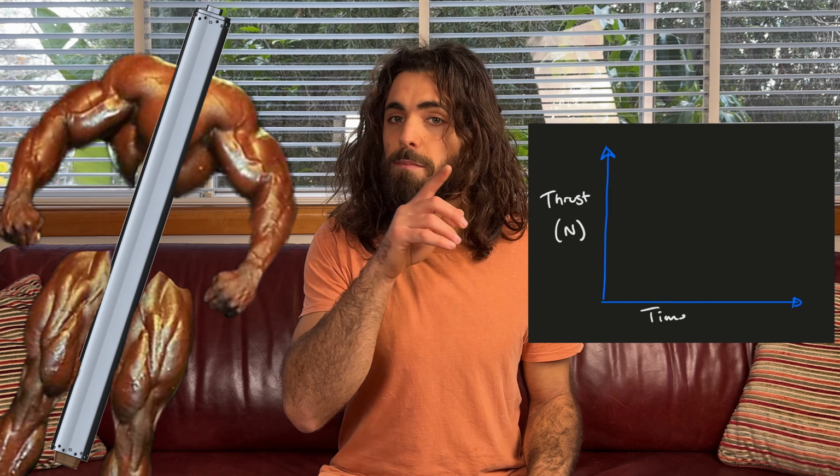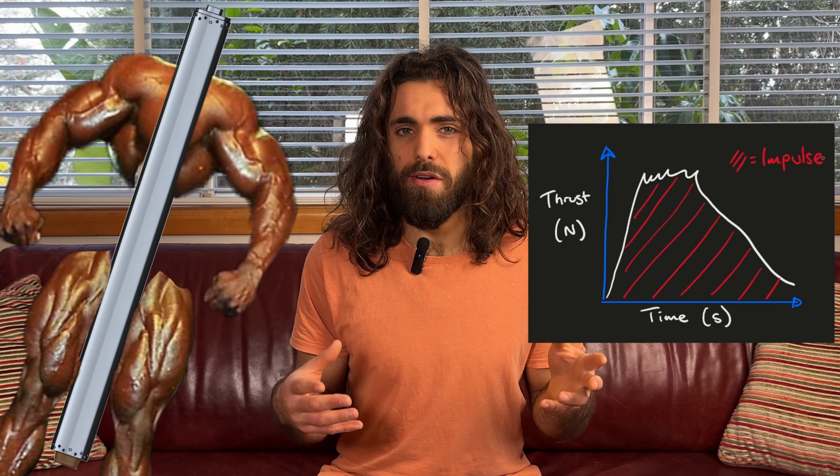You always want to design around the rocket motor, and this is because it's generally the most inflexible constraint in your design. What I mean by this is once you pick the size as well as the thrust output of the motor, everything else about the rocket kind of depends on these values. So just keep that in mind.